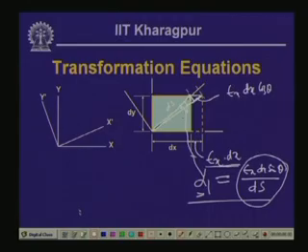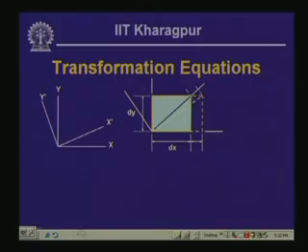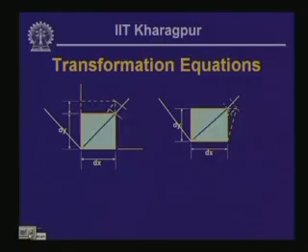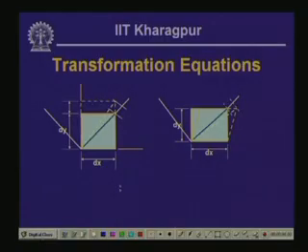Now, let us look into the deformation that we are getting corresponding to the other two cases. In this particular case, the deformation which we have of the diagonal, this is the original length ds, and because of the stretching in the y direction, this has taken this particular form, and thereby this is the extension in this particular direction, and let us call this angle change as alpha 2, and this angle change is in an anti-clockwise form, whereas in the previous case it was in the clockwise direction.